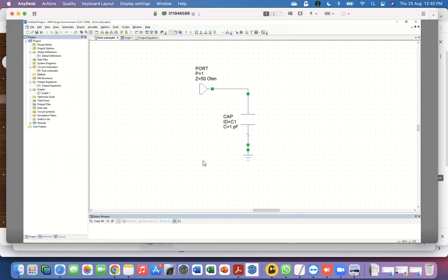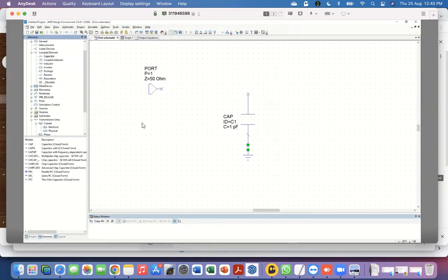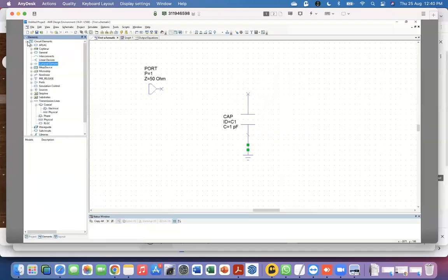I have some objects already here. One particular circuit which we are going to use very frequently for lots of things is a simple LC oscillator. Okay, so I already have a C there. So let me bring another component. Now we can look at this particular element window more carefully. So this is circuit elements. You can ignore these other 2 things for now. And in there's again a huge number of things. We will only be using a subset of these as part of this course.